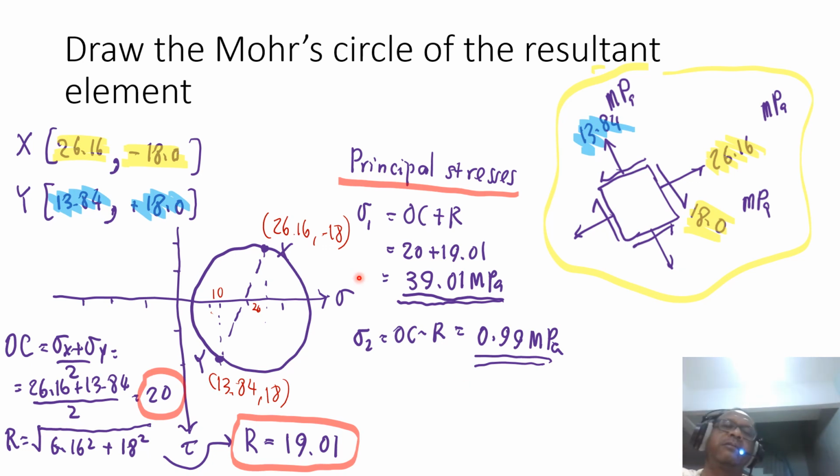So when we compare the results from these two approaches, we have got the same answer, where if we either rotate A to match B or rotate B to match A, we've got the same principal stress. We may not have the same Mohr circle, because the Mohr circle only represents the stress state of any point at a certain rotating angle. So what we find as the common answer would be sigma 1 and sigma 2, the principal stresses, i.e. the maximum stress and the minimum stress for the circles, are still the same. So we compare that, and you then